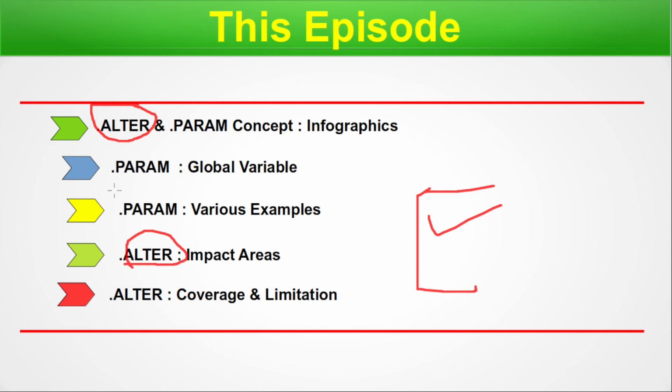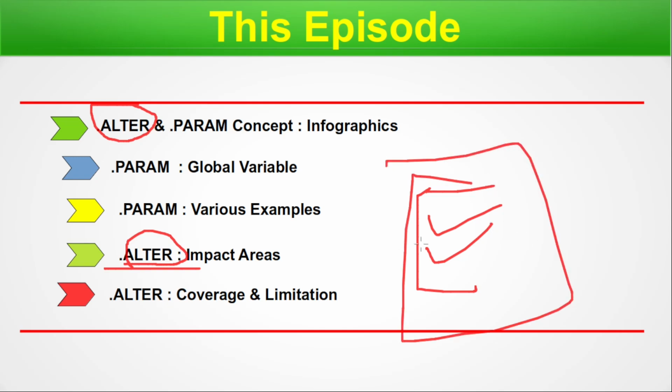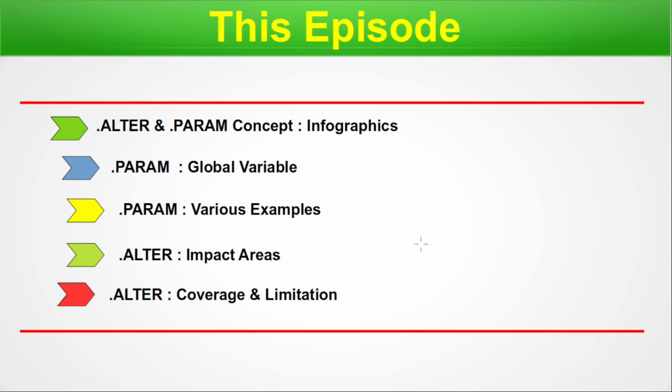And in multiple spice simulators, the dot alter is used as dot alter. That is why I am saying interchangeably dot alter and alter, because in ngSpice you will find it in the control section of the spice deck. So the concept or the philosophy of the alter is the same. However, syntactically it is used differently in different EDA vendor simulators. So you must be prepared so that whatever you learn here, theoretically that will be the same for all simulators. However, syntactically there will be some change from one EDA vendor to another EDA vendor. So without any further delay, let's begin.